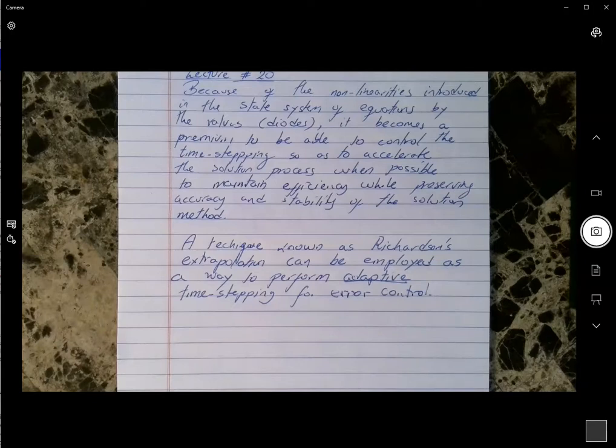And I know that it's going to produce instabilities, but let's see what I can do with it. So I implement the time step of 0.1 second, and then I go back in time, 0.1 seconds, and then solve again by using 2 time steps of half of that. So I'm going to take 2 half steps to the solution after 0.1 seconds, and then compare the two.